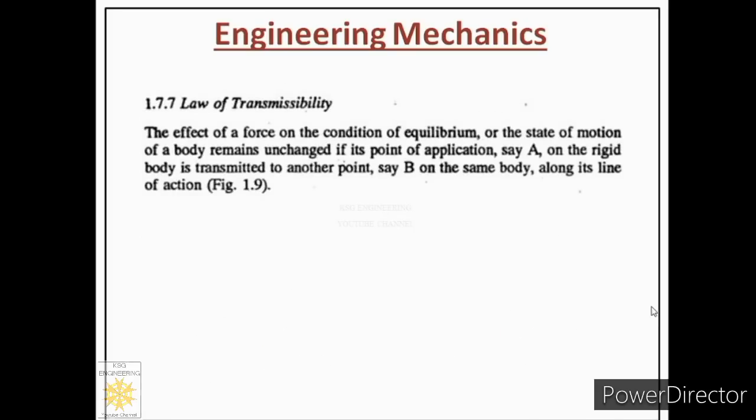Next is the law of transmissibility. This is a very important law. We will use this law in the problems. So let us read the statement. The effect of a force on the condition of equilibrium or the state of motion of a body remains unchanged if its point of application, say A, on the rigid body is transmitted to another point, say B, on the same body along its line of action.